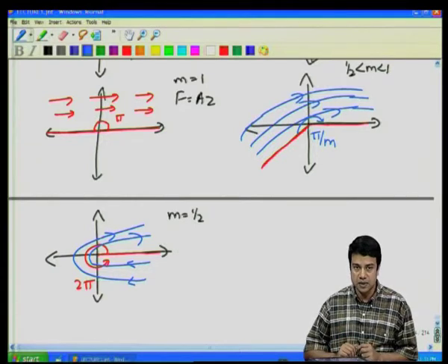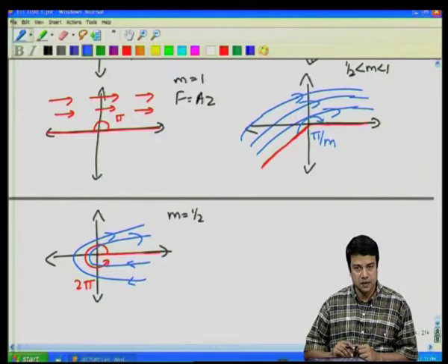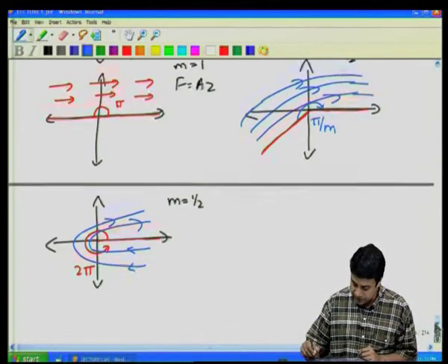At m equal to 1, it is just a constant velocity. M equal to 2 is a right angled corner, and greater than 2 is an acute angled corner, and less than 2 is a corner with angle greater than pi by 2. So, these are power forms of the complex function.